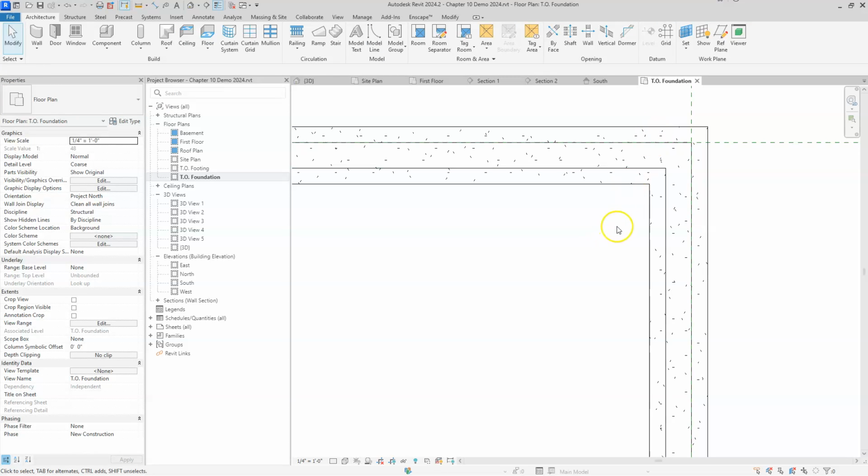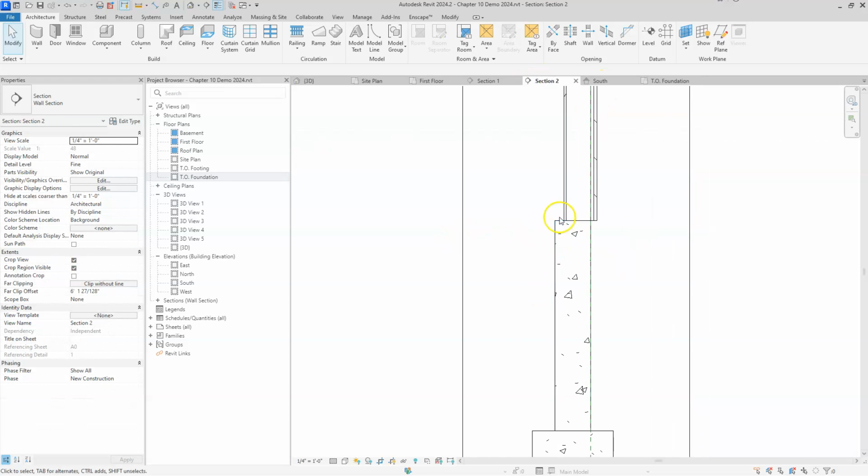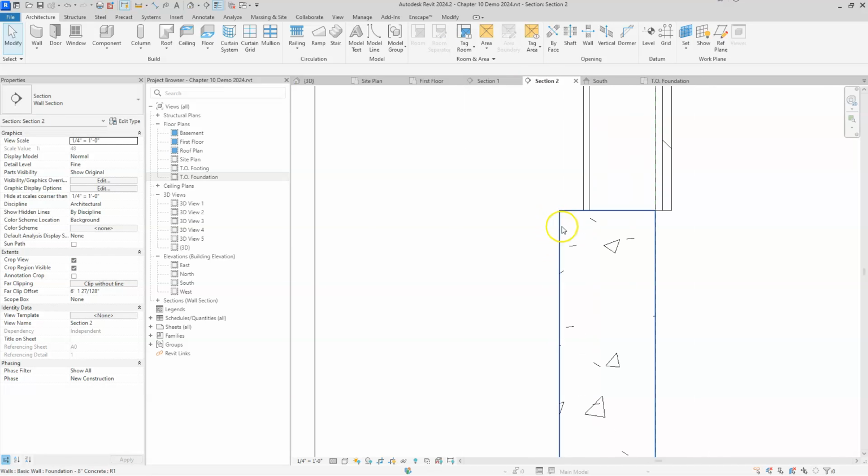So the floor, if you haven't already guessed, is going to run right up to the inside face of that concrete, because remember, when we said we're going to run it up and stop it right here. So the boundary of that floor has to stop right here. It can't go into the wall, and we shouldn't leave a gap between the wall and where the boundary is.